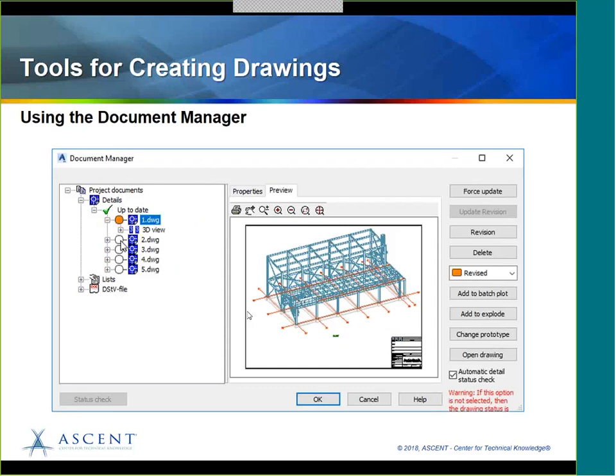And in the Document Manager, this is where you actually view and open your drawings. You don't actually open drawings outside of using the Document Manager. And this is because the drawings are all linked to the model. And so if you make a change in the model, it'll update automatically in the documentation as long as they have remained linked. You can have revisions, or you can just force an update. So let's say you're early in the project, there aren't revisions yet, you make a change, you just force an update. But later in the project, when it is an important thing and you need to set a revision, then you go ahead and pick your revision and set those all up. So that's also done in here, revisioning.